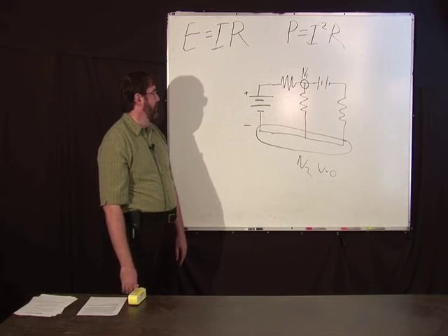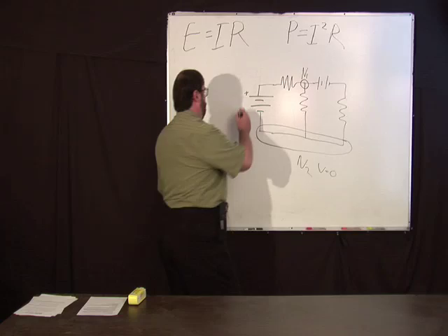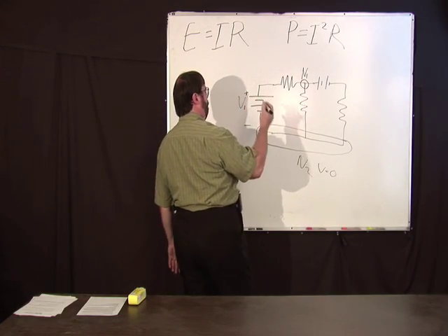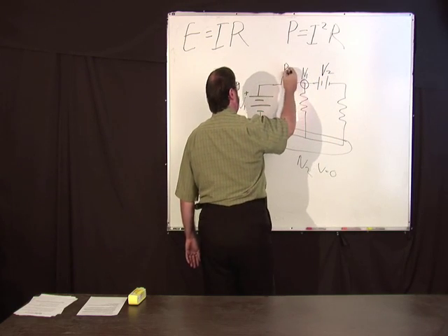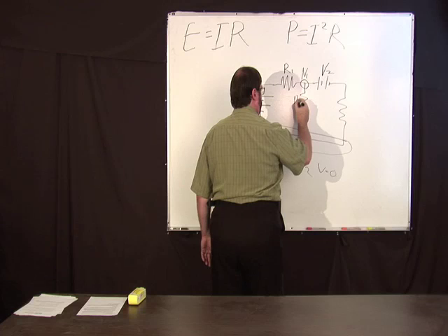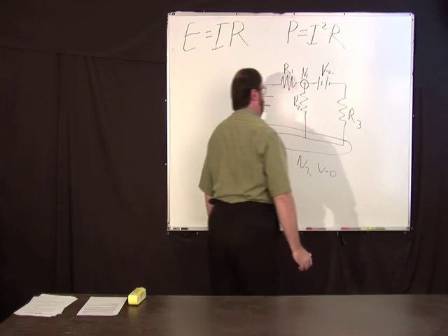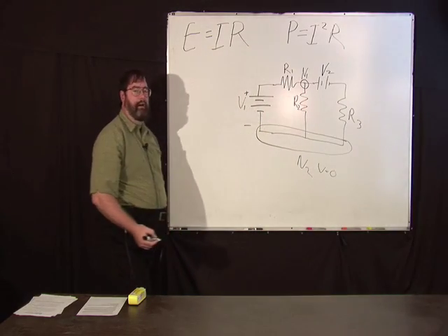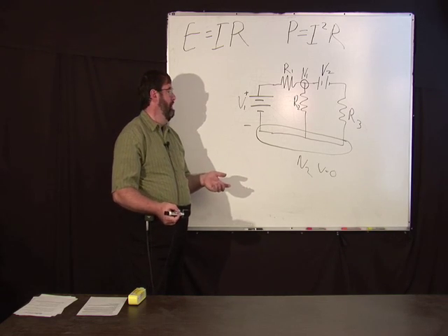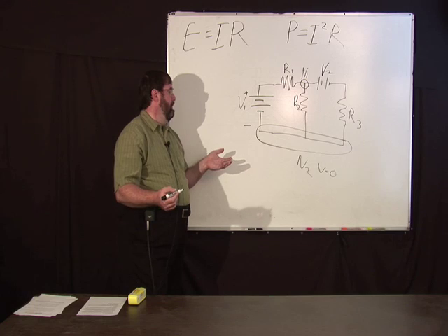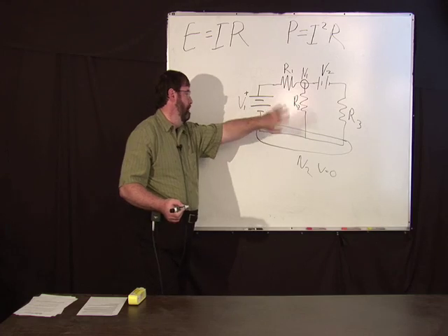The way this works is, let's call this V1, so we can sum voltage, make it quite general. Call this V2, call this R1, call this R2, and call this R3. Okay, just so we call it that. The first step in the mesh current method is to arbitrarily assign loop currents to each loop.